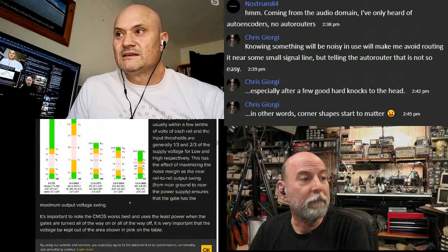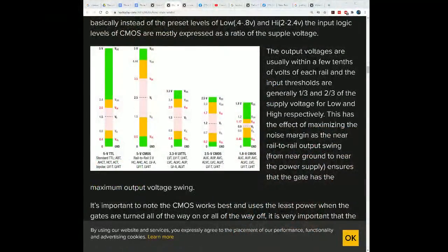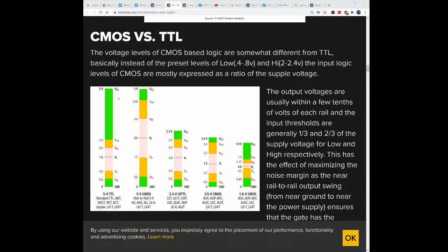So, moving forward, let's see if I can bring this up. Here we also have the voltages of the different logic families. Back in the day, everything was 5 volts, but we threw away all this green that you see here. This was all margin, right? And we paid to heat the part up with this additional voltage. So it only made sense to drop our voltage. And now we have a nice symmetrical usage compared to this 2.4, and the rest is garbage here.